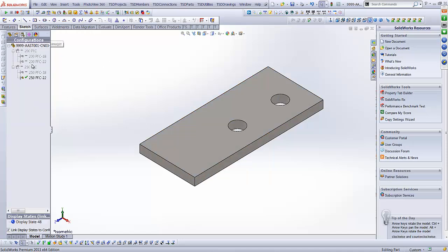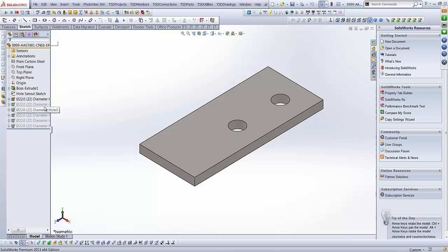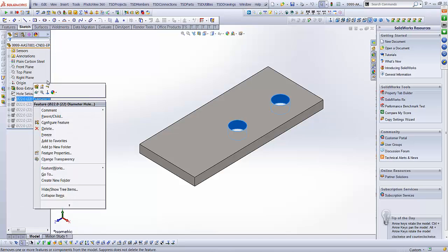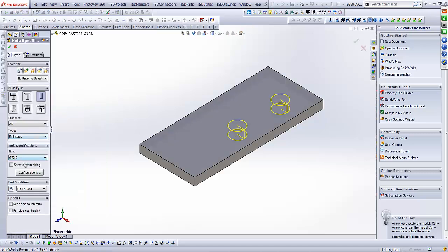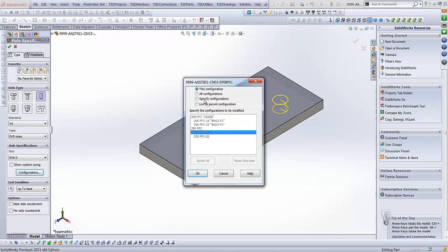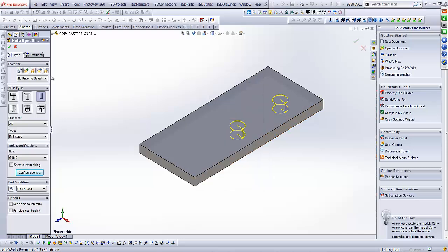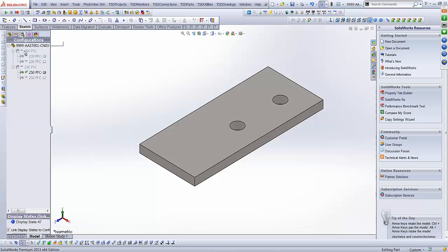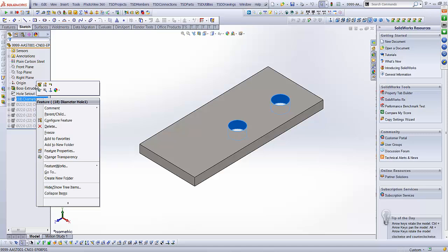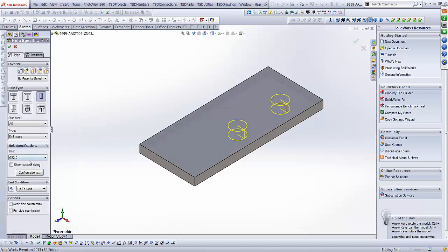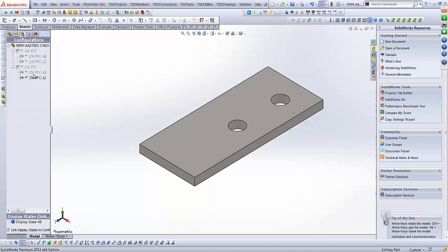And now we go back over to the 18. And we just need to make sure that we're actually changing holes too, which is another crucial process. So we're going to make them 18s for M16 bolts, and we want those too. So hopefully when we change our configs, the bolt holes change in size. Doesn't look like it's going to change. Let's just stick with custom sizing. It might be better for us in this instance. Hit my tick. That's a 22.